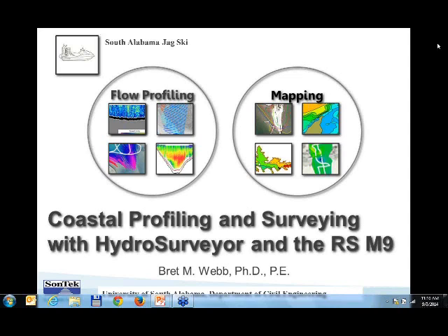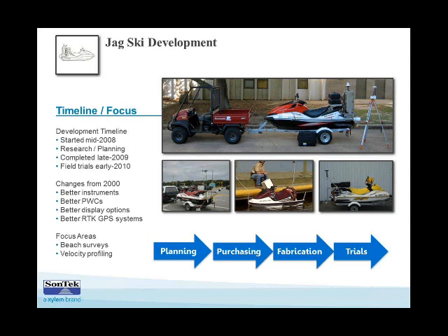We have a 3-seater, and one of the reasons why that is advantageous is that the size is a bit bigger, so it's more stable. It is heavier, which means that manual operation and lifting becomes problematic. But having the larger personal watercraft also means that as you add more instrumentation to it, you're not really affecting the stability and the buoyancy so much.